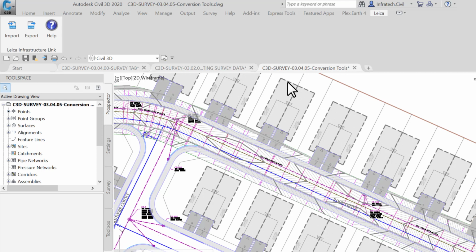All we have to do now is to switch to the survey controller to import the exported design file. Depending on the controller, this can be done through a flash drive, a USB cable, Bluetooth, a network account, or several other ways.